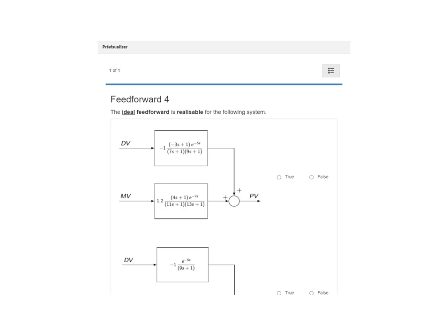If we look at this example, indeed we cannot have any problems with properness. If you take d over p, you'll have a proper feed forward. The delay in the process is smaller than the delay in the disturbance dynamics, and unstable pole zero cancellations come from a cancellation of the process.